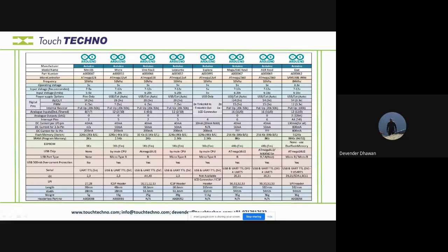Okay, and if you need analog input pins, we have those. Okay, if you need analog output, you see all of them are 0 except Duo. So you have 2 output pins also. So if you are looking for some analog output application, then this is your board. Then obviously the working frequency is 84 megahertz. So if you're looking for a fast application, then this is your preference.